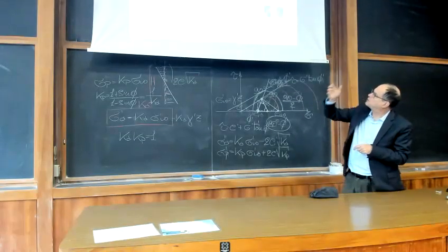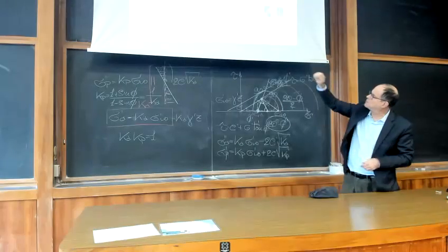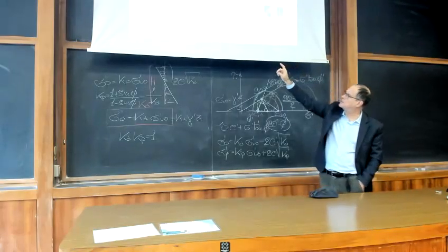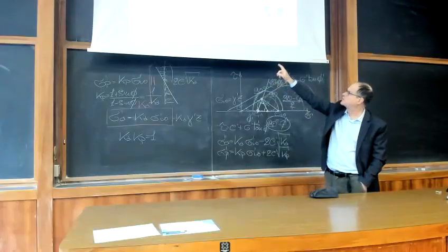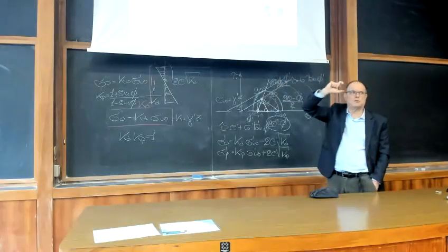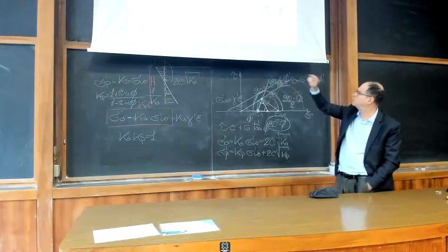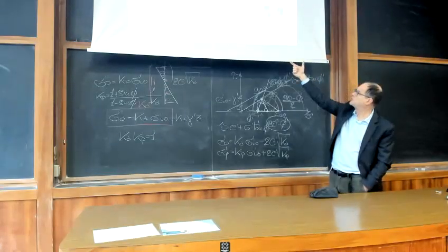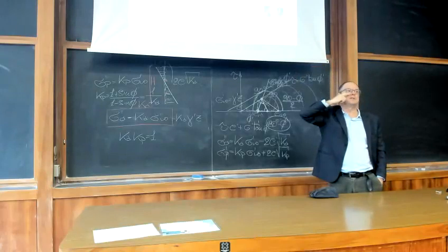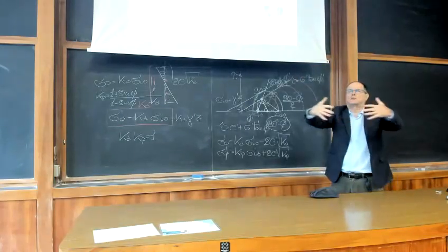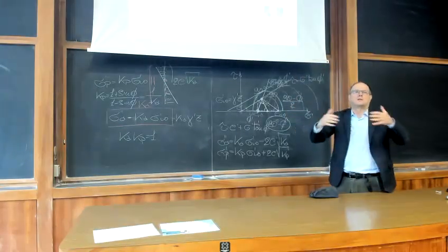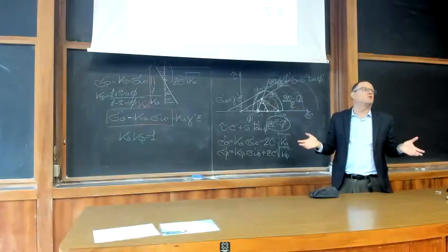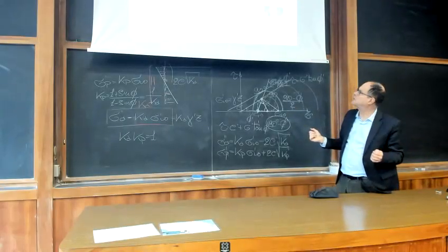Where does this plot come from? If you see, you have a dimensionless settlement, W is the vertical movement of your foundation, which is divided by your footing. In this case, it was a circular footing, so a diameter D. So let's assume that you have a circular footing, say 2 meters diameter.